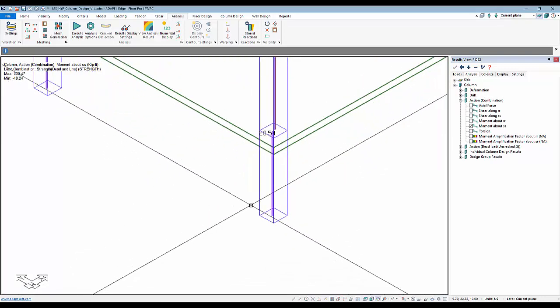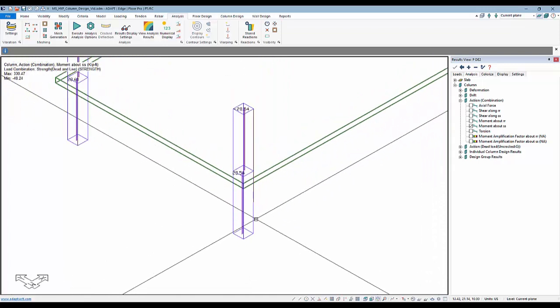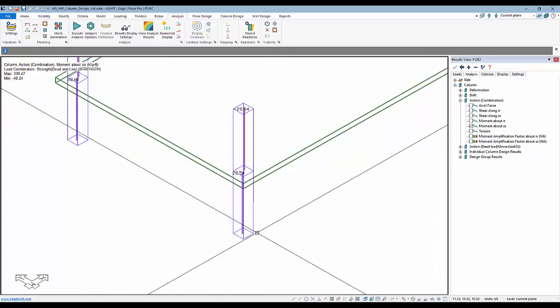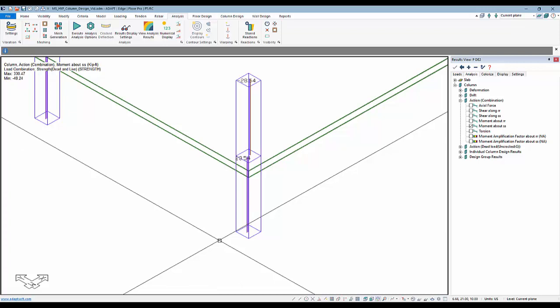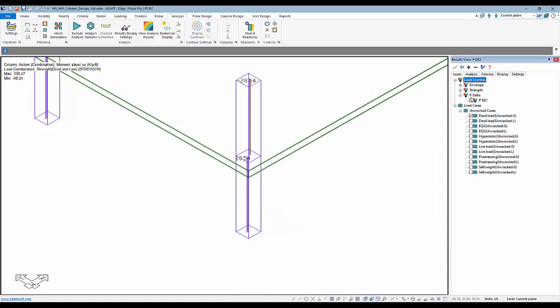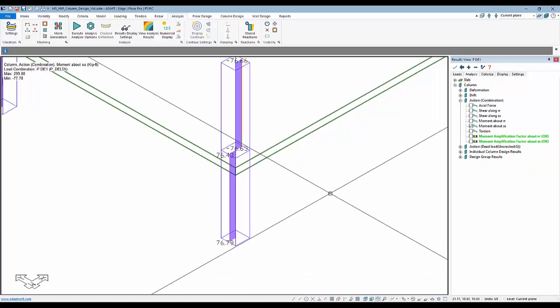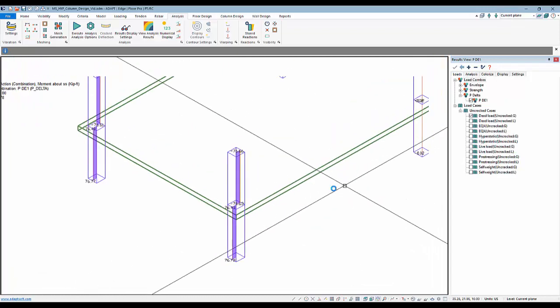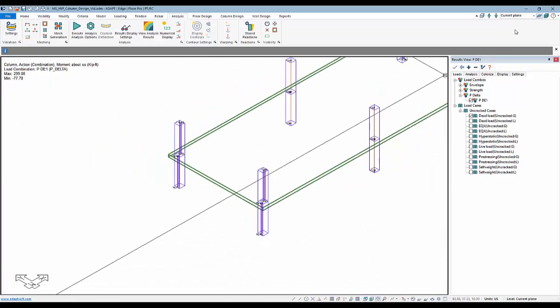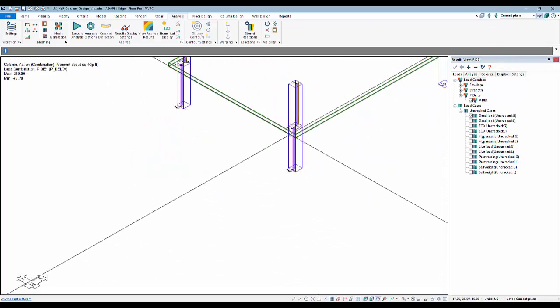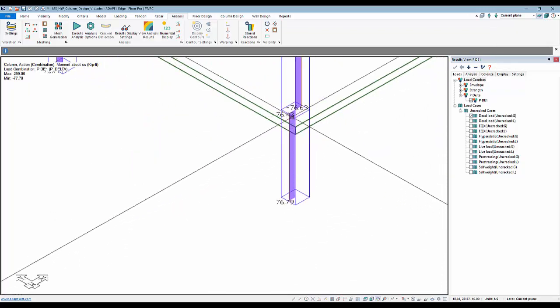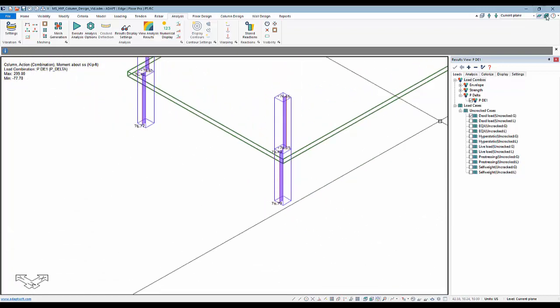Now if I use the graphical reporting tools, we can predict what the moment needs to be, moment SS, which is the controlling moment. We can predict what that needs to be and look like when we pass the data to S-concrete for the design. So I'll go back here to PDelta under PDelta 1, this combination here. I'll go to the combination results, moment about SS. And we need to go back to the global solution to see this. This is the moment for that combination with a single level run. So I need to come back to global.